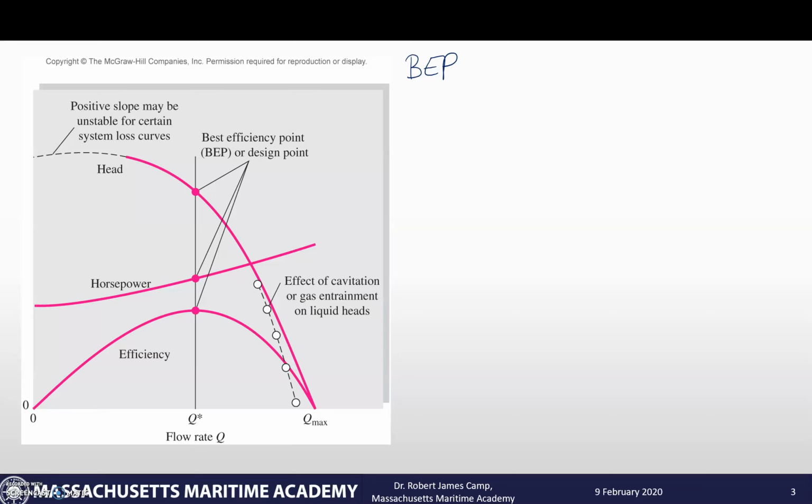We're going to go in, and on a couple of these curves, we're going to see multiple pumps on the same curve. So what's going on there is we're going to talk about this idea of geometrically similar pumps when we do dimensionless performance analysis. And it's basically kind of the same thing as using a model of a plane in a wind tunnel, where we're going to be able to predict what's going to happen on a larger airplane by what happens to that little airplane in the wind tunnel. But we're going to be able to do that with the pumps.